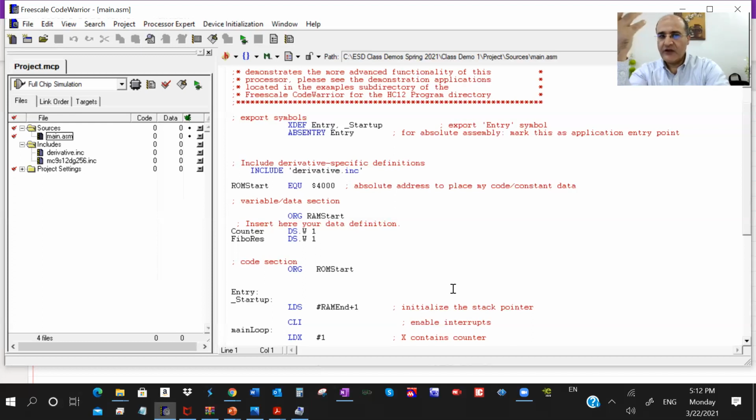So you should be able to reserve memory locations in the RAM, in the volatile memory, that you want to temporarily use. And there should be a place for the program that should be stored in the program memory, in the flash memory. In this case, they call it RAM start, ROM start. ROM here is the flash memory, not the E² RAM that is used for data.